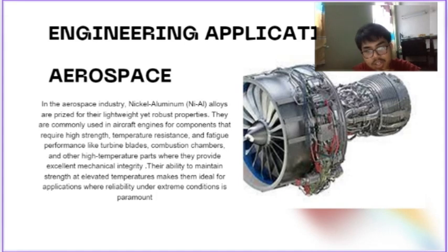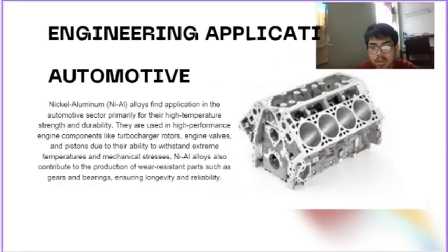One of the engineering applications for the nickel aluminum alloy is in the aerospace field. In the aerospace industry, nickel aluminum alloys are prized for their lightweight yet robust properties. They are commonly used in aircraft engines for components that require high strength, temperature resistance, and fatigue performance, like turbine blades, combustion chambers, and other high temperature parts, where they provide excellent mechanical integrity. The ability to maintain strength at elevated temperature makes them ideal for applications where reliability under extreme conditions is paramount.